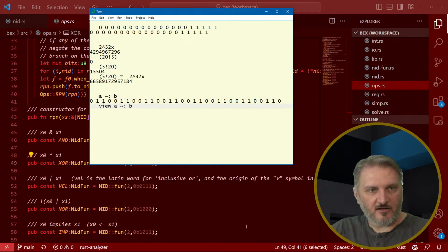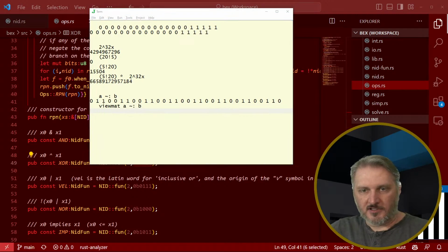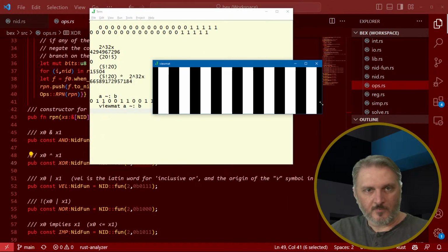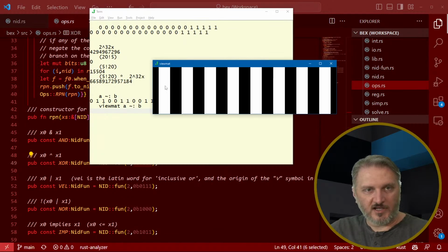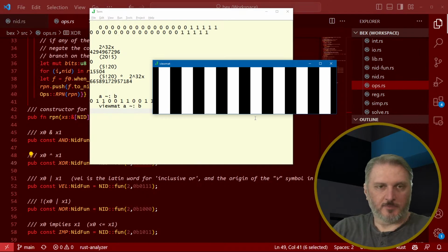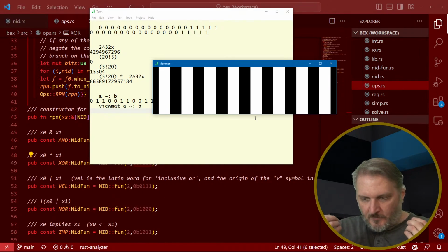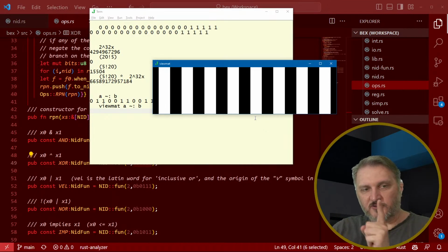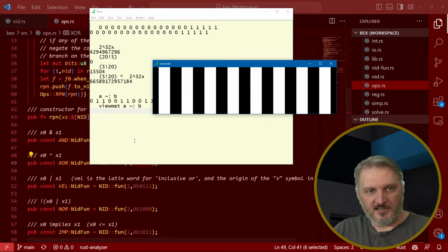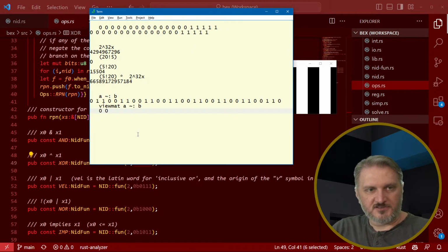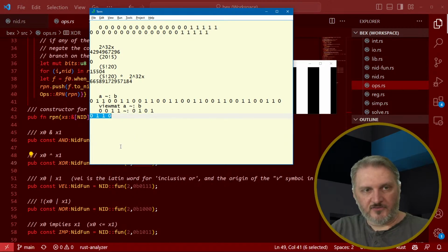Now, if you want to view map that, right, it looks like this. It looks like a stripe. Looks like a set of stripes. Actually, the white stripes, the ones are slightly offset, right? So it goes 0, 1, 1, 0, 1, 1. So yeah, that's the truth table. And it's just repeating. So I think of, technically, the truth table for A XOR B is 4 items long, right? It is literally, it should be 0, 0, 1, 1 XOR 0, 1, 0, 1. And so it's that.